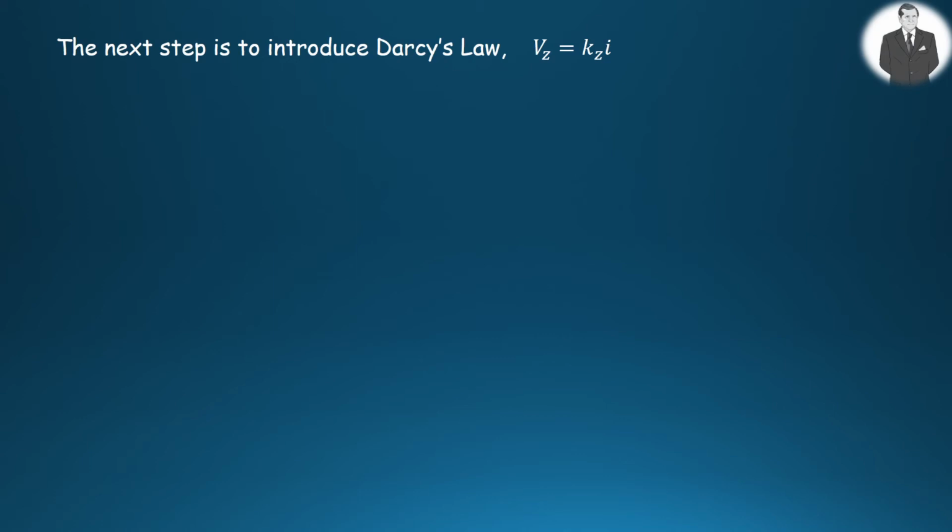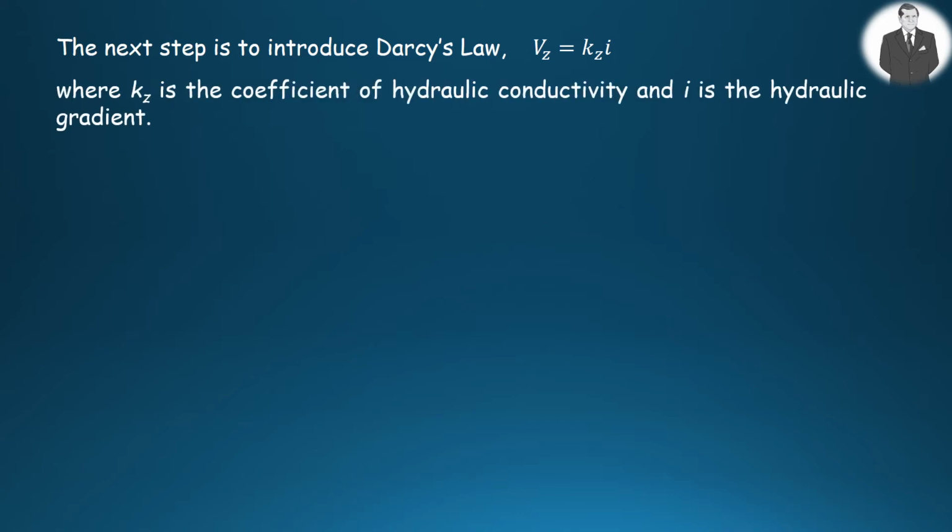The next step is to include Darcy's law, which is equal to K sub z times i, where K sub z is the coefficient of hydraulic conductivity of soil, and i is the hydraulic gradient.